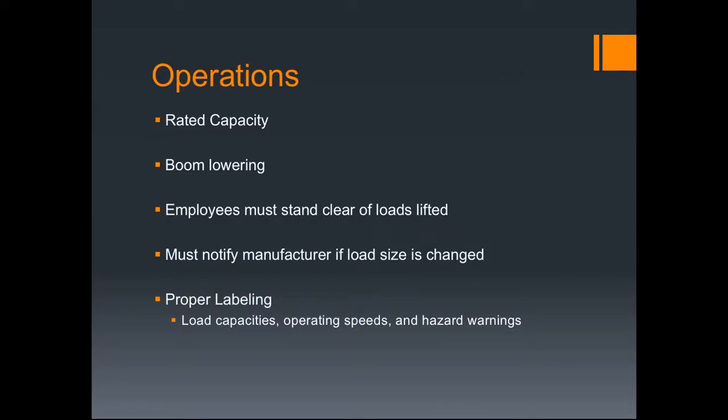When you're operating the crane itself, there's a rated capacity listed by the manufacturer of the weight that the crane can hold. So you must make sure that whenever you use a crane, you let the manufacturer know what that weight actually is. And if that weight changes for some reason, if you have to add or take off any part of that load, you must let the manufacturer know, because this could change how the crane is set up. Because if the load changes, the crane could move or tilt because of this change. So just to be safe, make sure the manufacturer knows at all times what that capacity is.